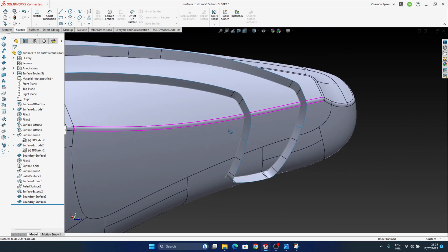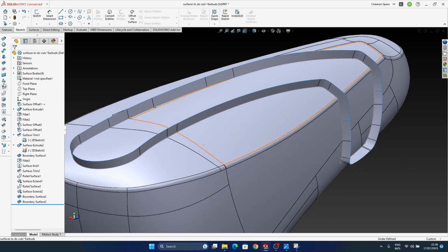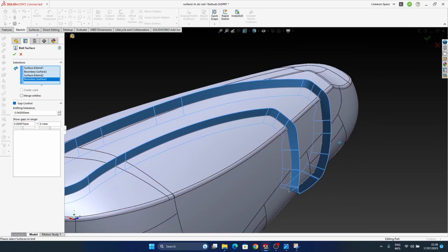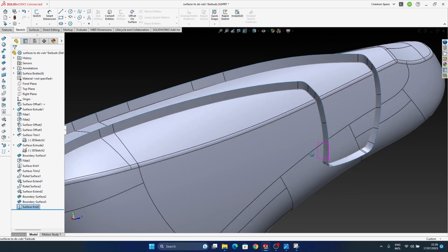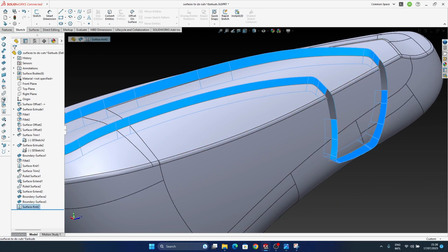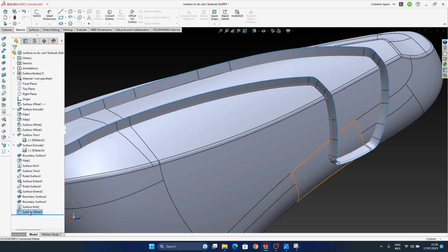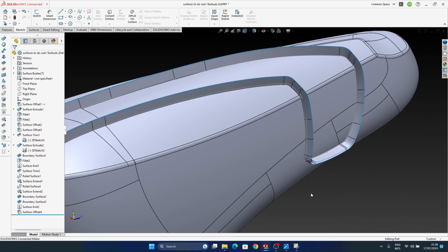Right, so we are here. Okay, so we did the first surface to use for the cut, or almost. Yeah, so I'm going to make a joint surface, knit surface cut, when I'm going to get used to it. Okay, so here I'm going to make an offset 0.2. Remember, it's on both sides anyway, and I think I have the option to say on both sides. No, I don't. Oh, I have to do it twice.